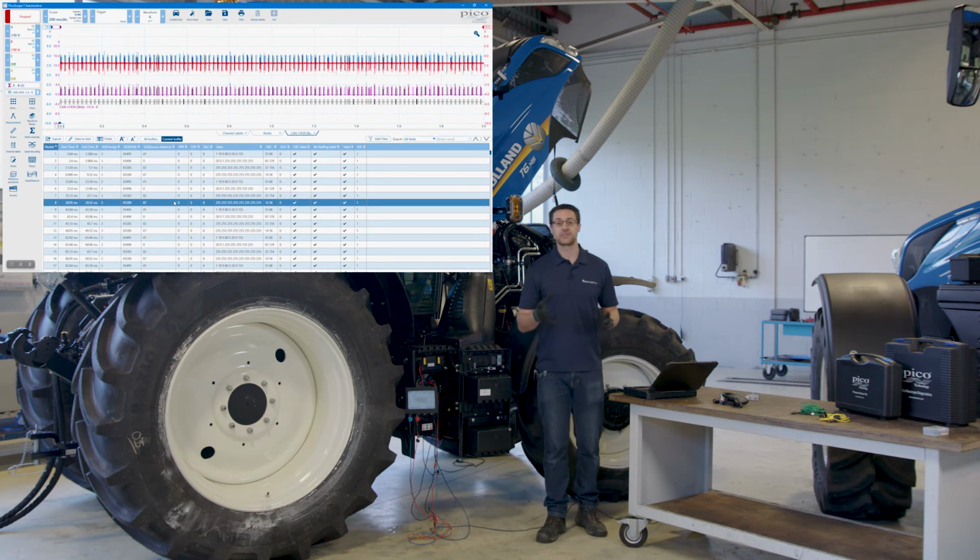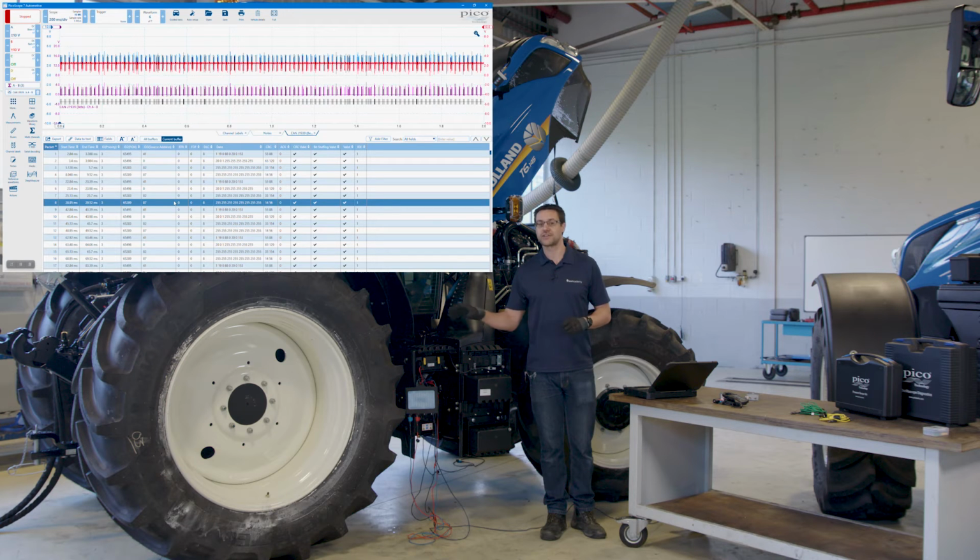There's a fantastic website out there called isobus.net, and on there is actually a standardized list of all the PGNs that are potentially out there. Obviously, there will be proprietary ones on certain machinery. Of course, there will be. They have to protect some of their data. But for the most part, you can get a lot of this stuff. So the source addresses are also on there.